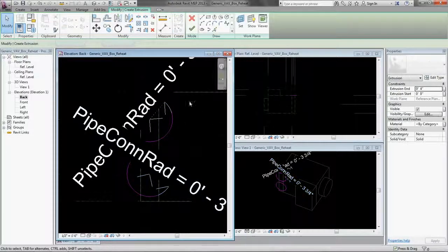This is one where I'm not going to make a parameter for how far they extrude because I feel like it's not all that important to be able to change that, and the fewer parameters I have polluting my family, the easier it is to work with. So I'm just going to say that they're sticking out of the box about 4 inches and call it a day.